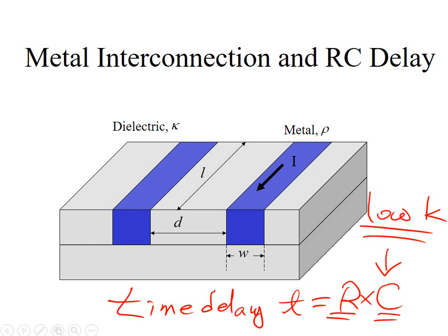When the geometry reduces in size and you try to keep up the capacity to hold the charge carriers, you need to have high K dielectric materials. On the other hand, when the dielectric material is not used for a charge storage device, it basically serves just as an insulator between two wires.